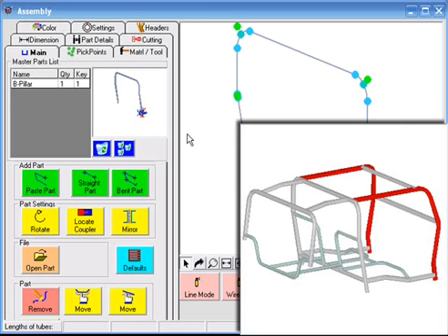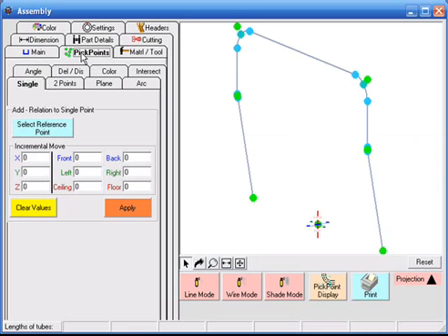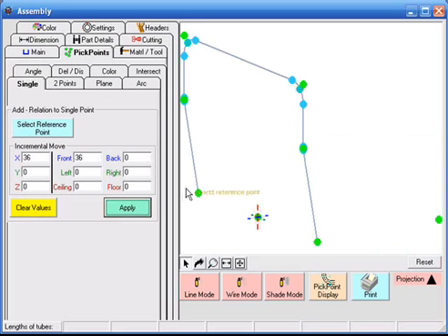We are now going to define our 2 uprights. Same as our B-pillar, we define points to create the part. Our base point is 36 inches away from our B-pillar. Our first bend is 1 inch towards the back and 8 inches towards the ceiling. BendTech will automatically calculate our bend angle or any rotations that might occur.